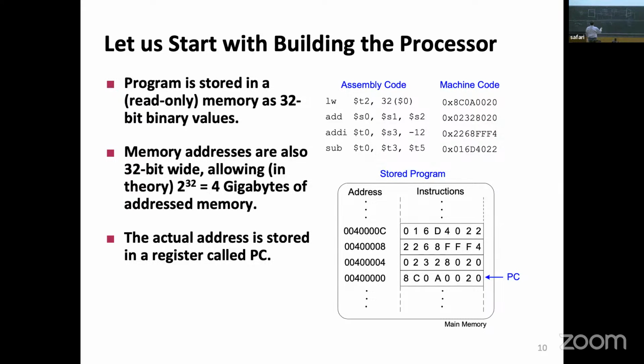So when I'm doing an R-type instruction, I am choosing this address, 1. When I'm doing a load word, I'm choosing the other guy, this one. So the address to which I will write will be picked up from this register. And this control signal will tell me where I'm picking it from. Hopeless? Don't worry, I'll do it twice more.